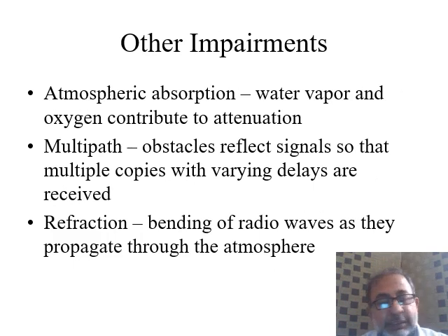Other impairments that a communication over wireless would face are the atmospheric absorption, which is due to the water vapors and oxygen. I've already talked about it, that the water vapors and oxygen have their own separate characteristics of absorption of electromagnetic power, and it varies with the frequency, and both of these exhibit spikes at certain frequencies also.